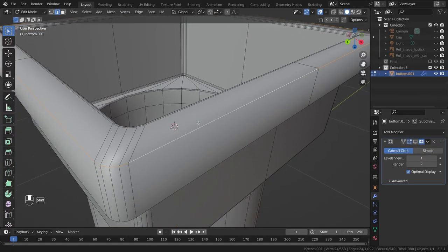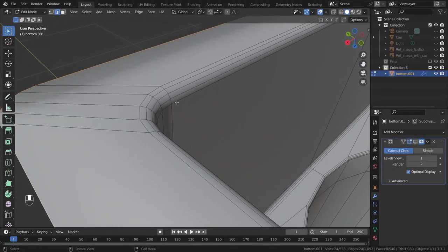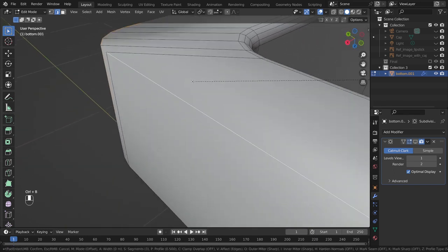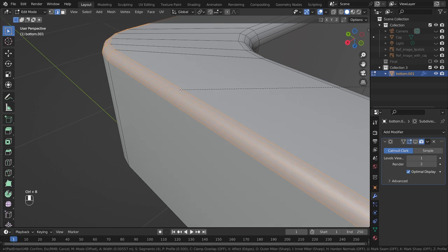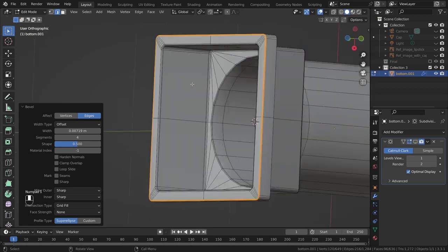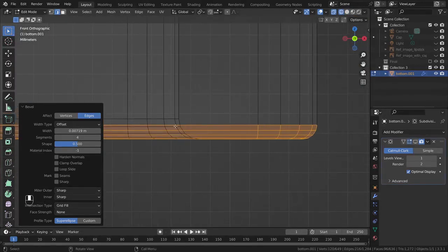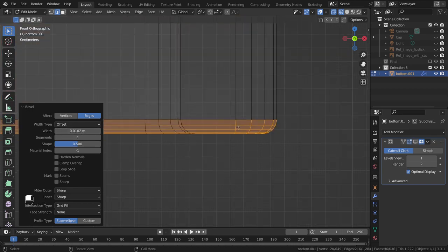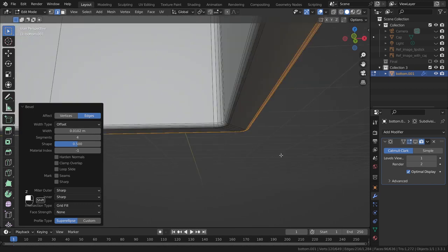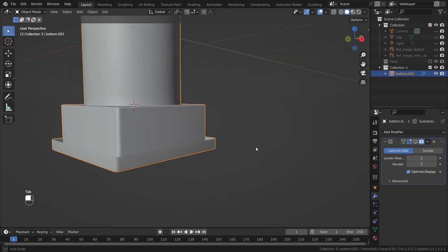Now, what do we do? We just create a bevel, and I want to keep it kind of the same as this one here. So we know that we have 5 edge loops here. So Ctrl B, and then create 5 as well. Same size is a little bit hard to see. You can go to the front view and then kind of match them up, right? We can kind of see here what is happening. So the width should be around the same size. That looks fine. And that actually looks quite great.